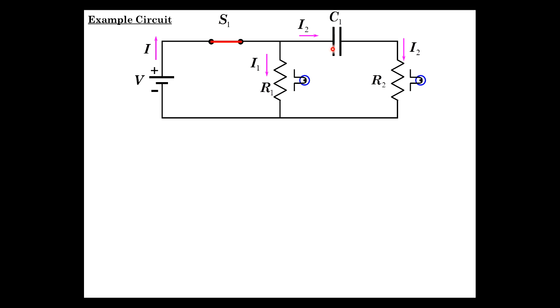However, as this capacitor builds up charge, it pushes back on the source that's trying to put the charge there in the first place, which is the power supply. And so it pushes back harder as more charge builds up on here, pushing off charge here and continuing the current. So when that's built up enough, it pushes back so hard against this that it stops the flow. So I just kind of gave you all the answers there.